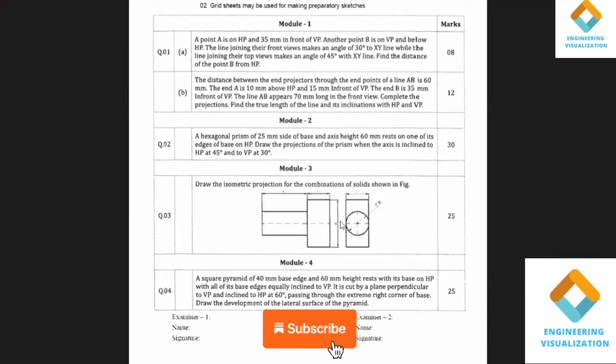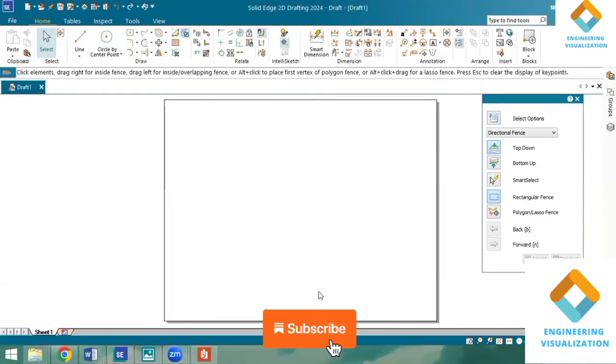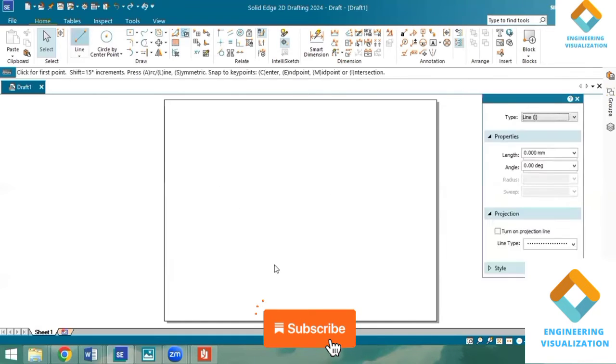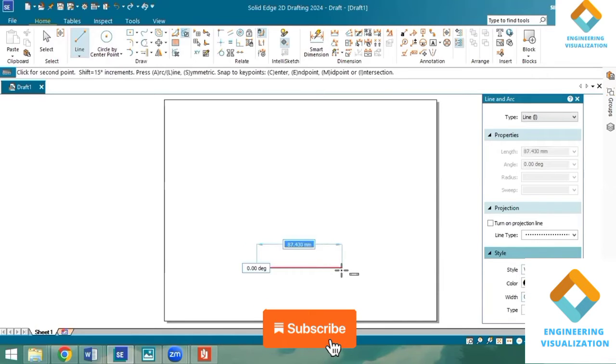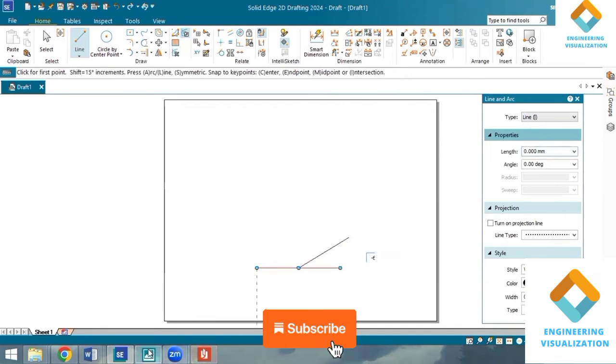Combination of cylinder and rectangular block. Okay, so to construct here, first we need to take one horizontal line as a reference. From this reference point I'll draw one line with an angle of 30 degree. So here I'll take 60 mm. Angle we take 30 degree because in isometric we should use angle 30 degree. First I'll be constructing a rectangular block.